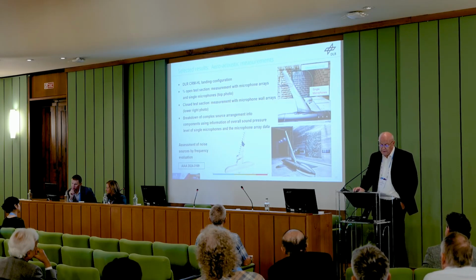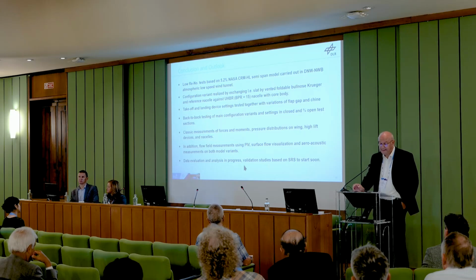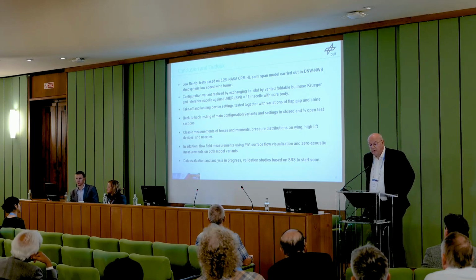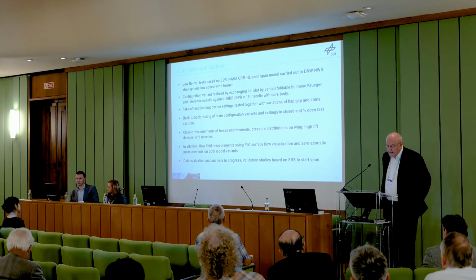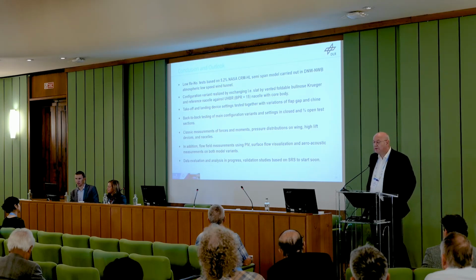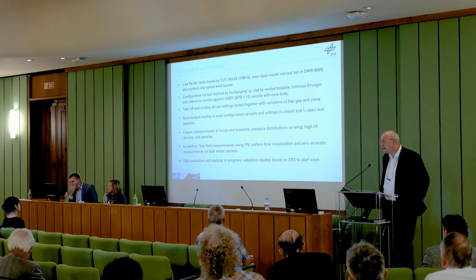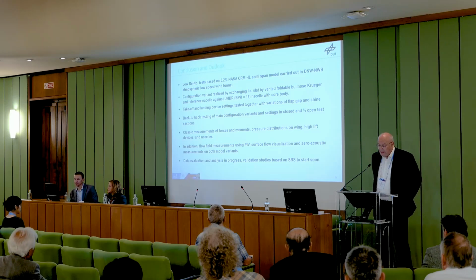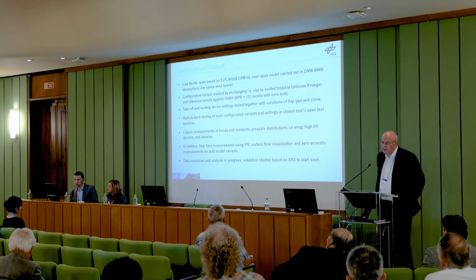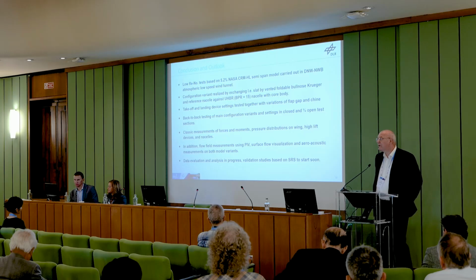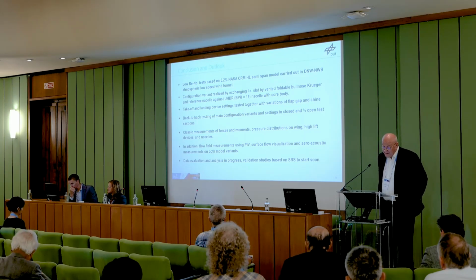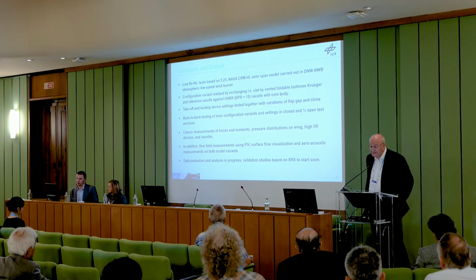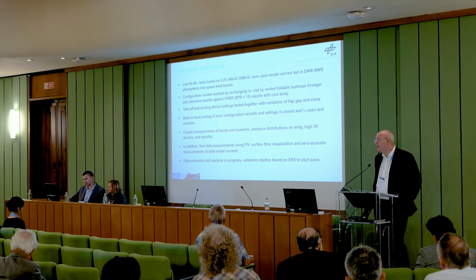All right, this brings me to the conclusion and outlook. We did some low Reynolds number tests with a 5.2% semi-span model in the low-speed wind tunnel Braunschweig. We introduced a configuration variant with a modified leading edge and a different nacelle, and did combinations of both. The UHBR nacelle is representative of a bypass ratio of about 15. We looked at takeoff and landing device settings together with some variations of the span-wise flap gaps.